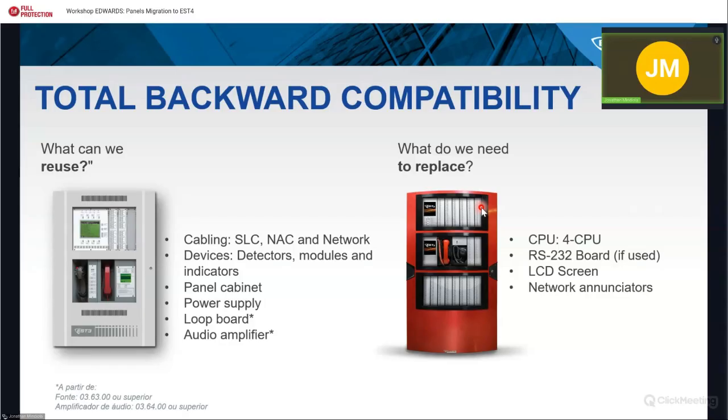In the EST3, all the cards were installed in the hardware layer. The LCD screen of the EST3 you installed in the hardware layer, the loop boards in the hardware layer, the power supply, the LED switch card, everything you install in the hardware layer. Also the microphone, also the fire telephone, you install in the hardware layer.